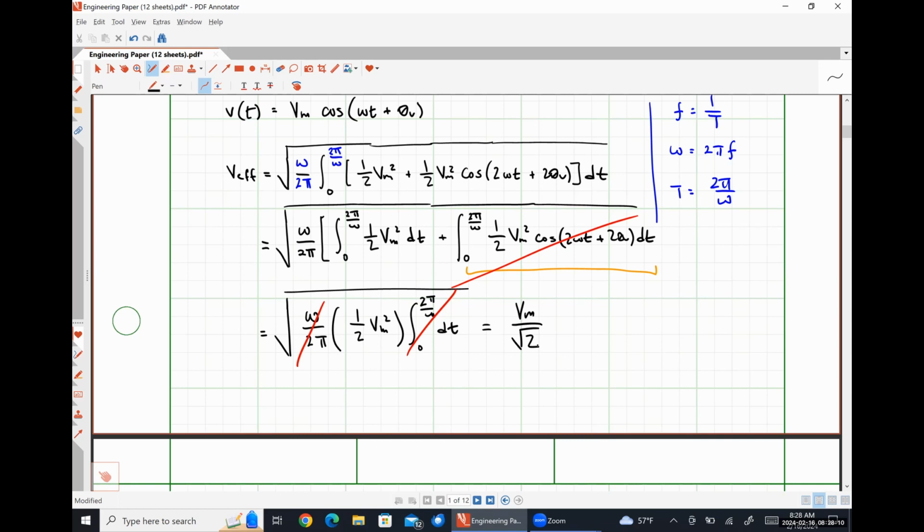So anytime we have a sinusoidal signal, the effective value is just going to be the magnitude divided by the square root of 2. Why that's super great is because here in the States, we work on a frequency of 60 hertz. In Europe, it's 50 hertz. Two different omegas, but effective values get rid of that, right? So it does not matter where you are in the world, analysis done using effective values is going to be consistent regardless of what your excitation frequency for your system is.